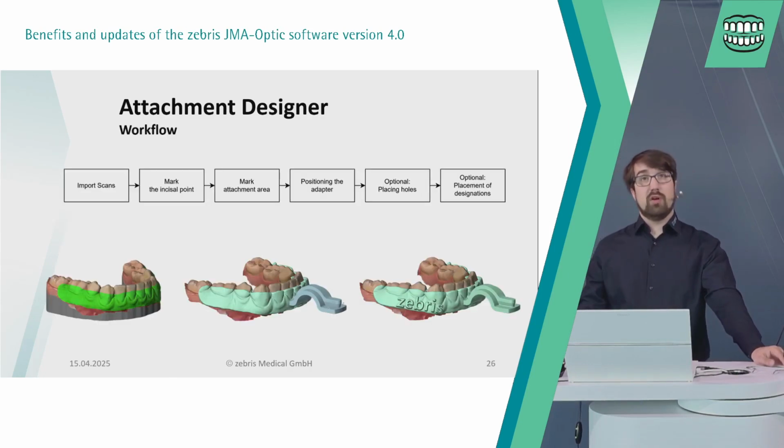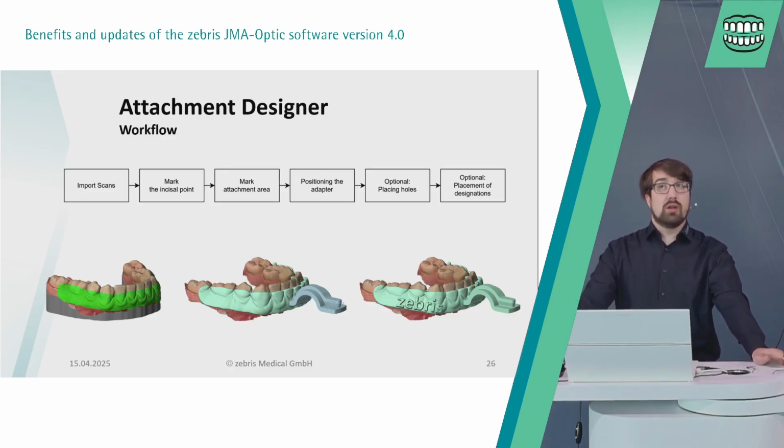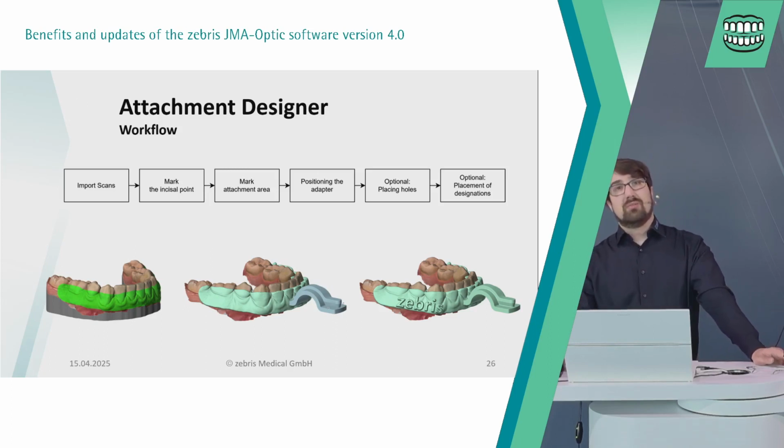The design workflow is really simple. You import the scans, mark the area where you want to have attachments, and position the adapter in the front. You could place some holes onto the attachment to insert some adhesive material through the attachment, and you can also place some text on the attachment so you know which attachment belongs to which patient.